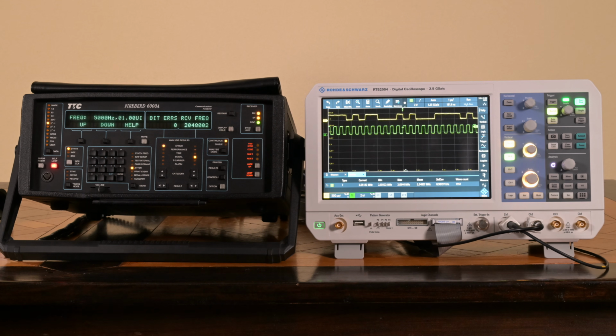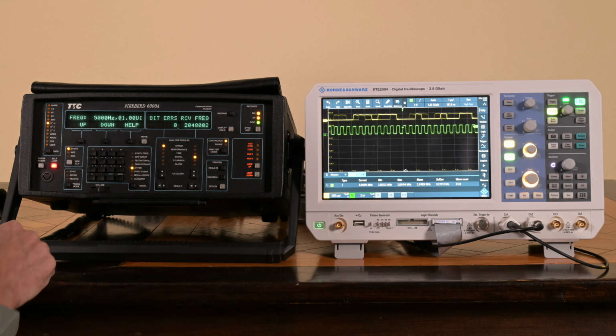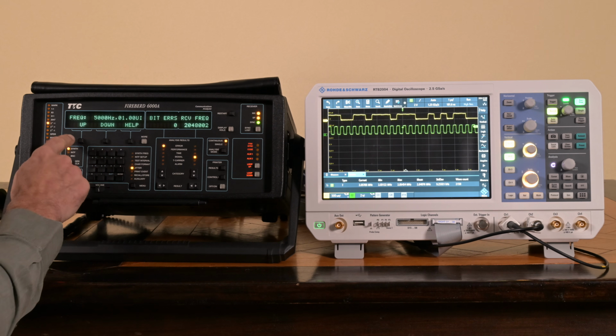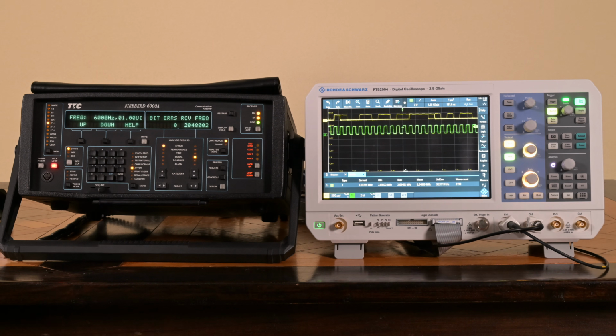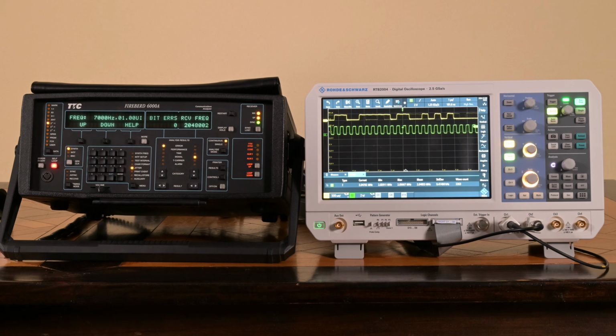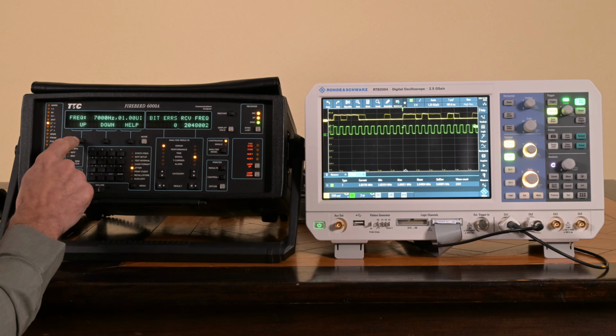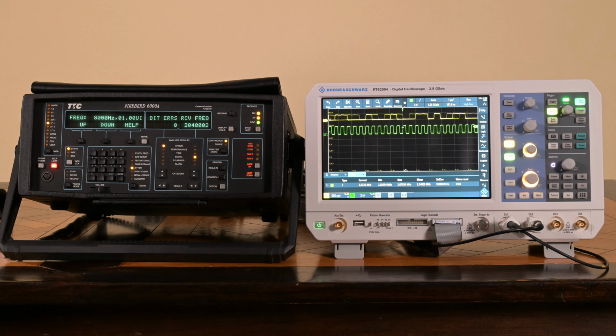So now let me play around a little bit and try to find a point where the telecommunication protocol is not tolerant anymore to the amount of jitter that we're adding. You can start all the way down at 10 hertz, but I know at 5 kilohertz it's still going to work. I'm going to bring it to 6 kilohertz. The protocol is still doing well. I'm going to bring it to 7. It's still good. I can also use the numeric pad here. 8 kilohertz.